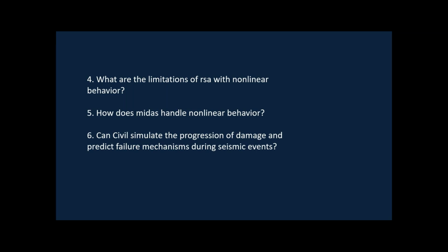But if you mean the progression of damage in the form of failure mechanisms, or the pattern in which plastic hinges develop in a structure under a seismic event, then yes, MIDAS Civil can assess the mechanism of plastic hinge development and predict the damage depending upon the type of hysteretic model that you have given.